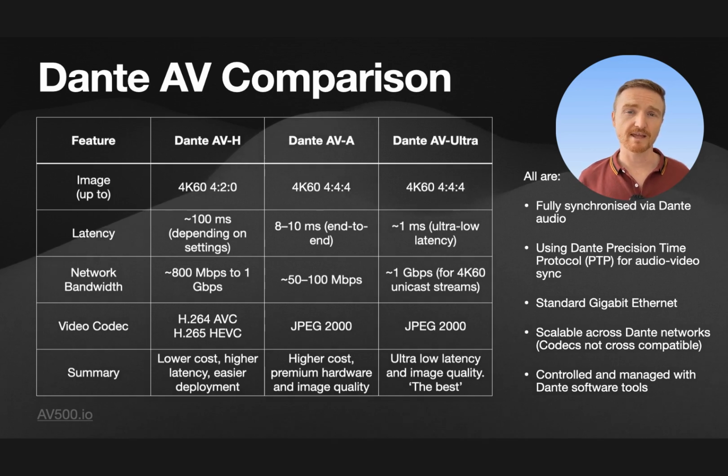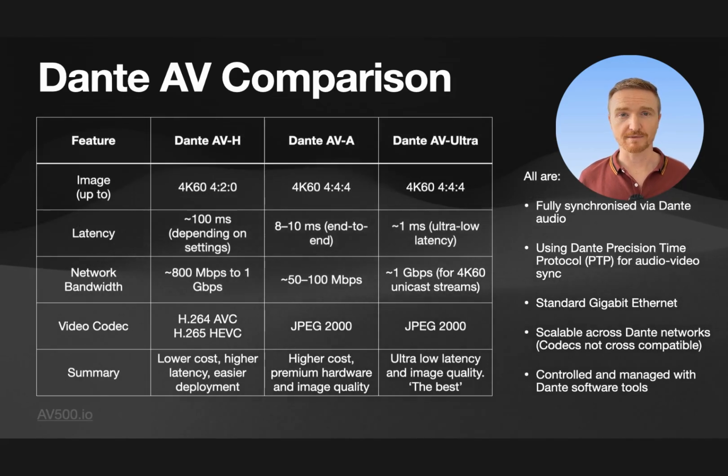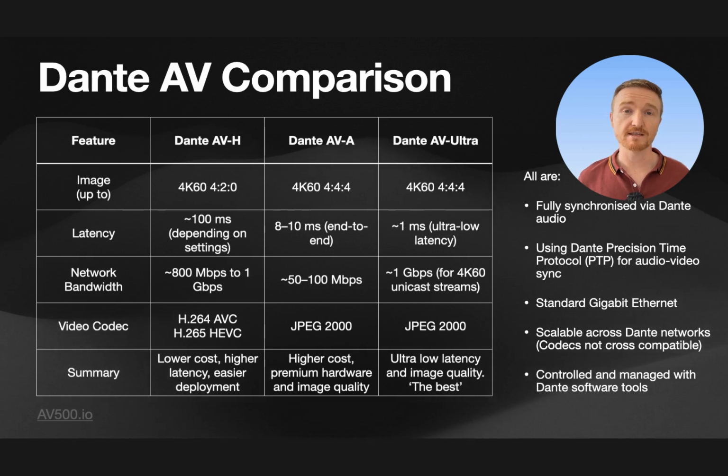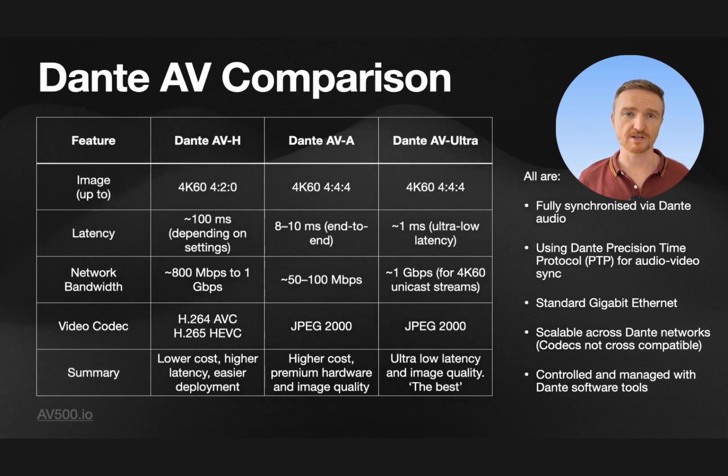The idea here being that existing H.264 hardware can be updated with just a software update from the manufacturer, allowing it to become a Dante endpoint without requiring a specific Dante chip on board. It's just a software thing. This allows these existing devices to become part of the Dante ecosystem and enables interoperability with other Dante devices. This means adding auto discovery, doing routing via Dante Controller, as well as remote management via Dante Domain Manager. Great for existing installations where the AV team is already used to using Dante tools for managing their audio. They can now patch video anywhere inside of the site.